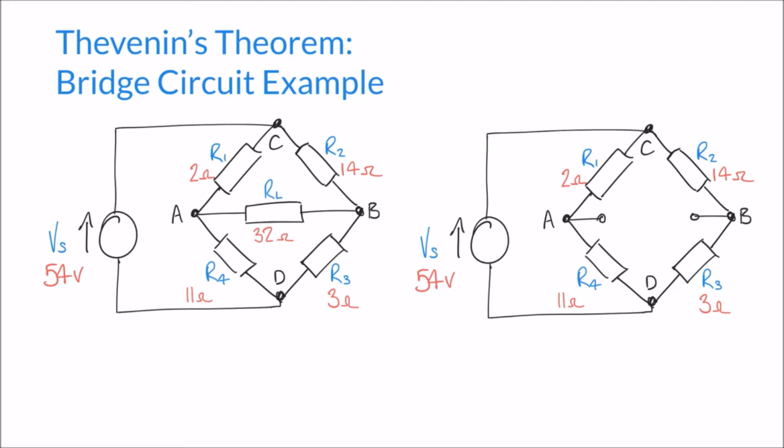For those who remember our previous videos on Thevenin's theorem, the first step of Thevenin's theorem was to find the voltage across the terminals using the potential divider rule. So in this case our terminals are here, and likewise we can still use the potential divider rule in order to determine the potential difference across these terminals, remembering what we said about a balanced circuit earlier on. If our circuit is balanced, we would expect our result, our voltage across these two terminals, to be zero. Let's see if that's the case in this particular example. To begin with, it might help to redraw this example very quickly.